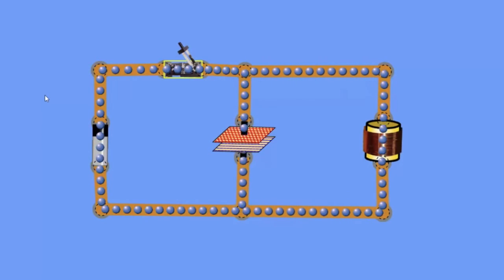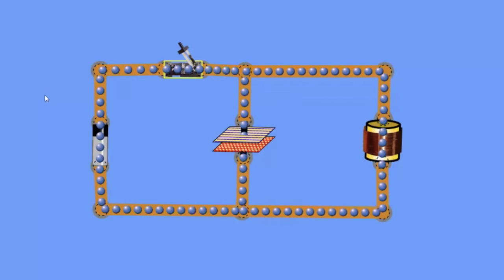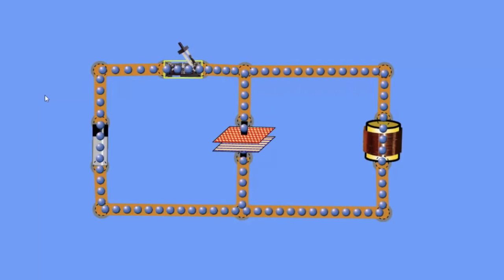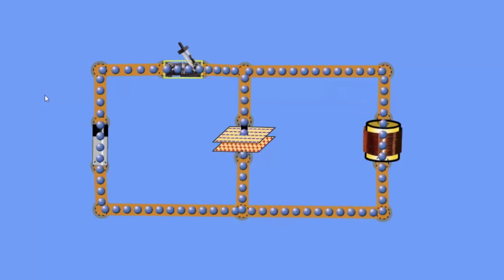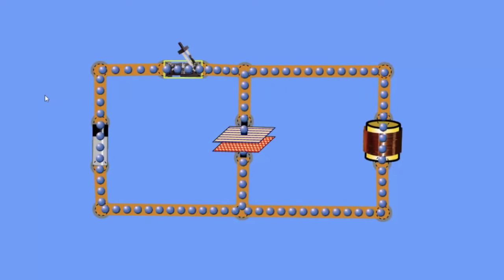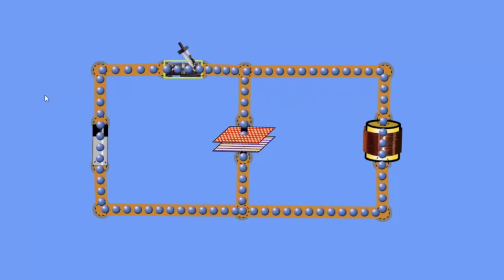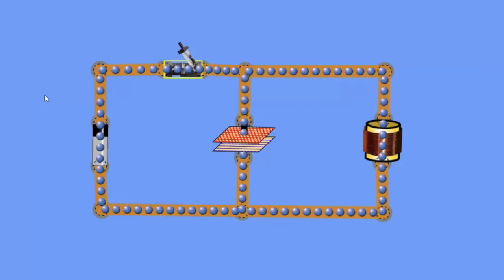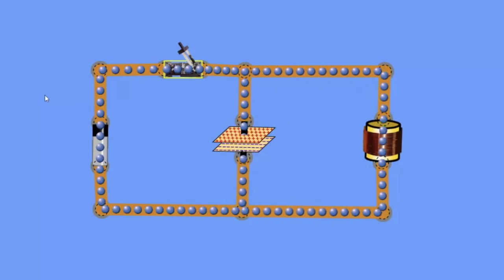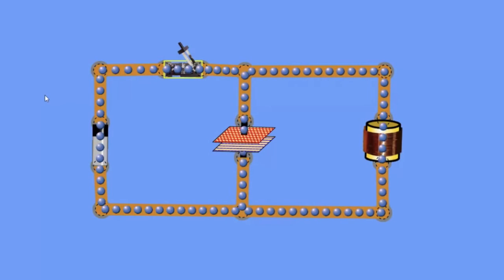That higher level of current is being opposed by the magnetic field set up in the inductor. As the capacitor discharges, the current reduces. When the current reduces, the inductor supplies its energy to push the current along, and it charges the capacitor to the opposite polarity. So your inductor is fighting the change. Your capacitor is enabling the change. It is a continuous back and forth, and this is the basis of what is referred to as a simple oscillator or a timing circuit.